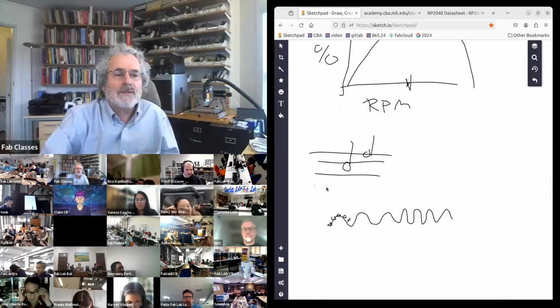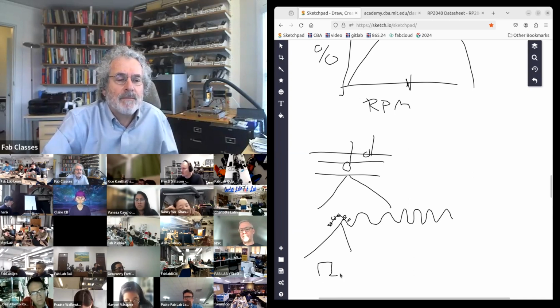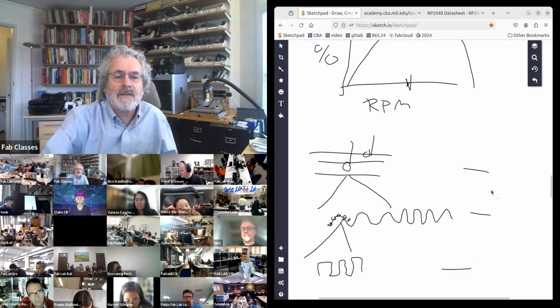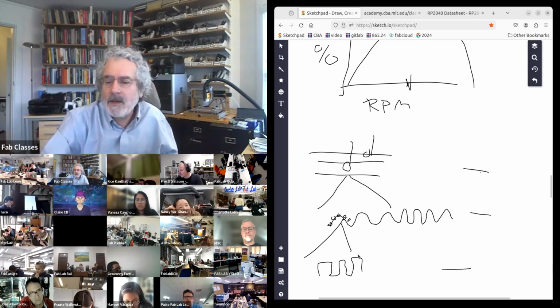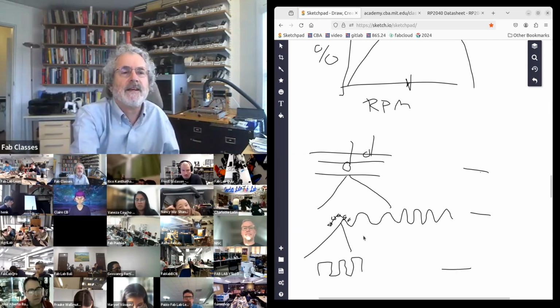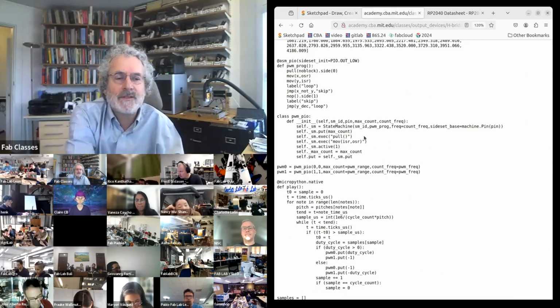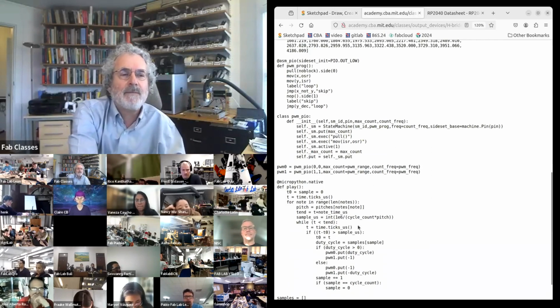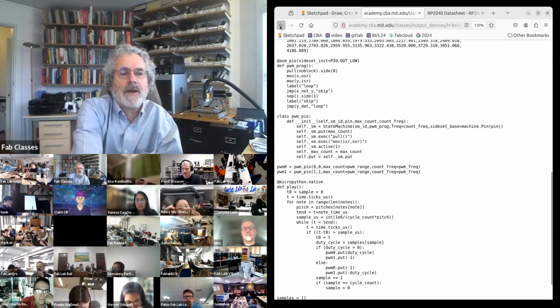we had the notes, and one note turns into the waveform, but then one sample in the waveform turns into the PWM pulses for the current. So we've got 3 different time scales: notes, waves, and PWM. And for that to work, the PWM has to be at a very high frequency. So I'm using the PIO generators to make high frequency PWM generators. And then I'm using that to do the wavetable synthesis. And so in that first example, I was playing the sine wave.